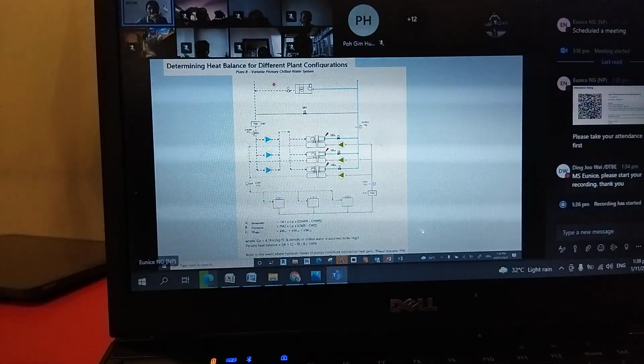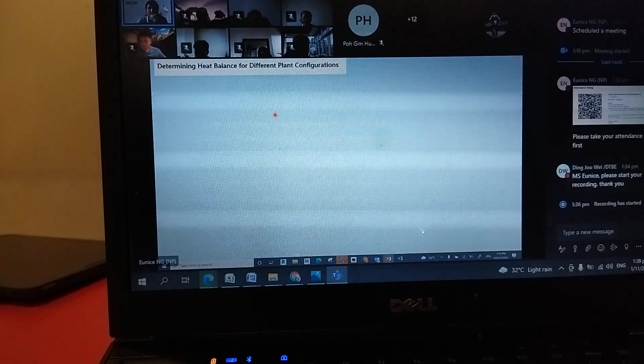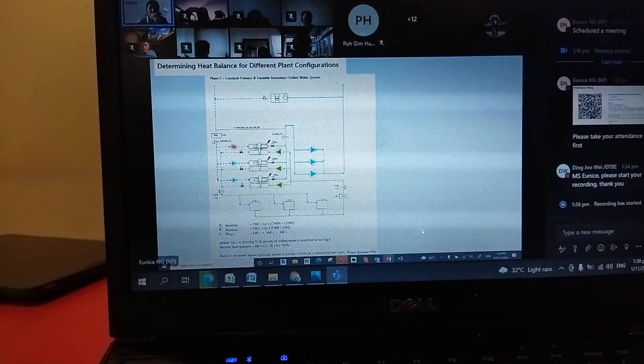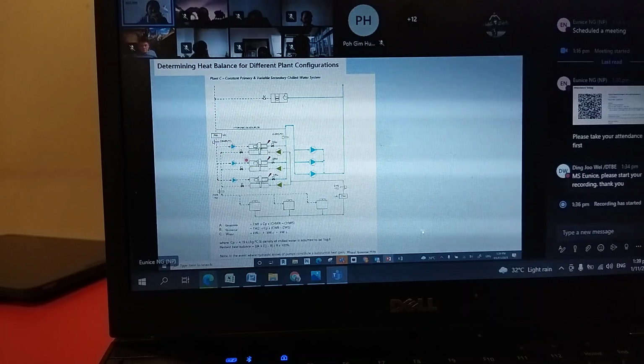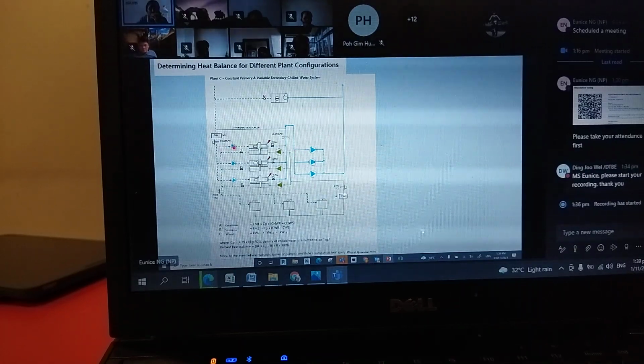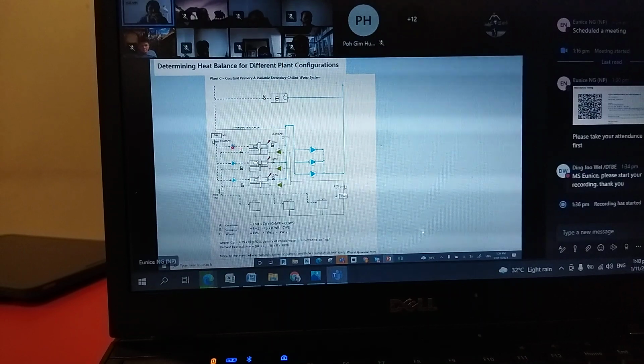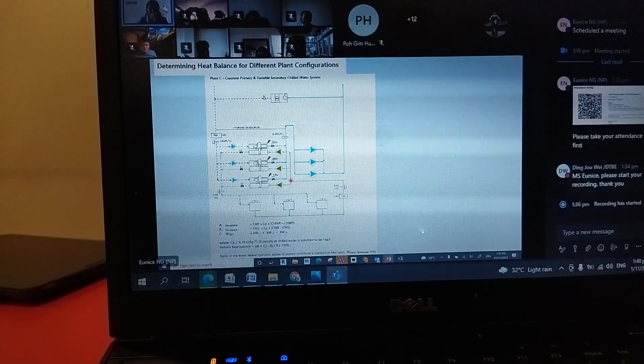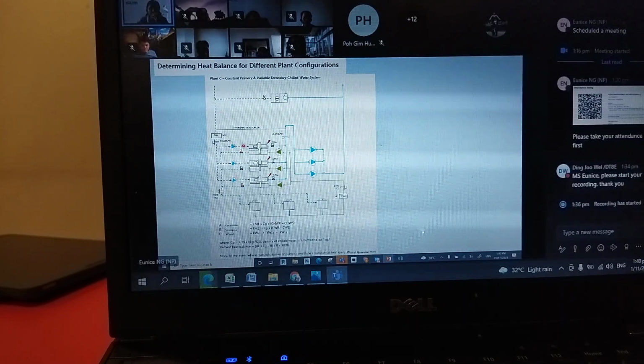The critical path of the next one here. You can see that this pump is now smaller, it's actually drawn smaller in size compared to this one. This pump itself is responsible for the chilled water that flows through the chiller only. Through the chiller only. And this one can be constant speed, because the flow through the chiller is still constant.